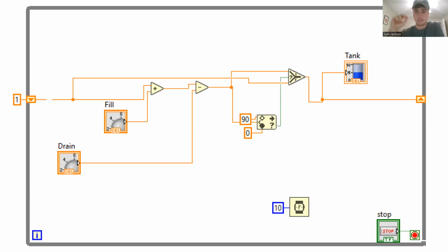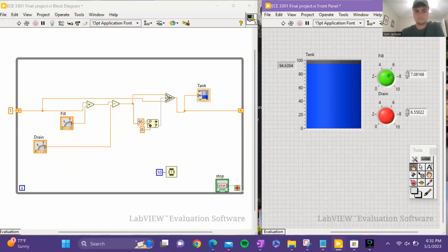It never actually would hit 0.00 or actually hit 90, because in industrial applications, especially plants, those are the absolute maxes and mins that it can hit. And so it would be dangerous for safety and for the health of the tanks and the systems being used to actually hit those max and min, which I think was an important feature that is a part of SCADA.